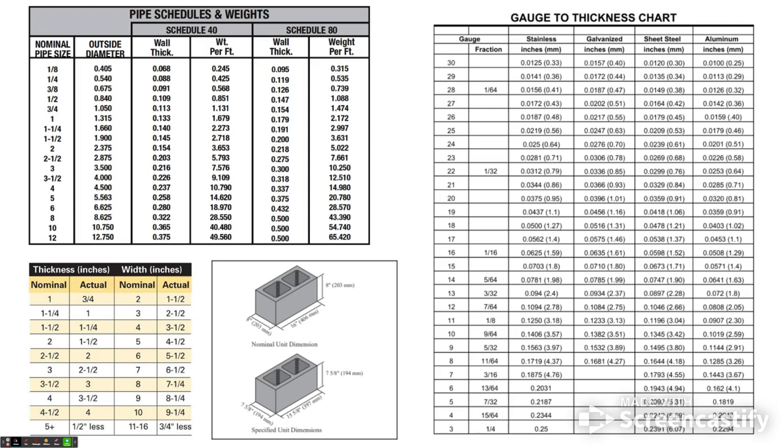When you're thinking about 2x4s or 2x6s, usually those don't actually measure 2x6 or 2x4. They actually measure about 1.5 by 3.5 or 1.5 by 5.5. And those are considered nominal sizes. It's just kind of industry jargon that has developed over time that we use to refer to those particular boards and that type of lumber.